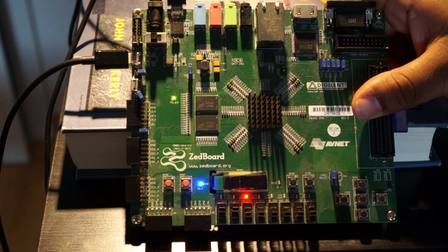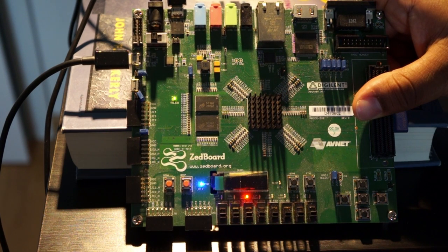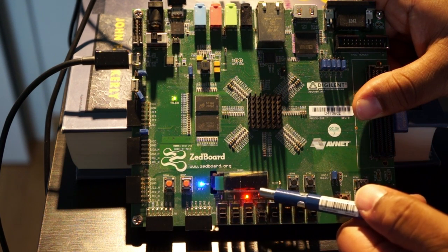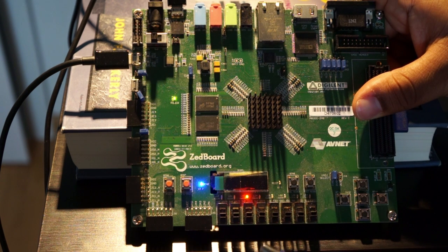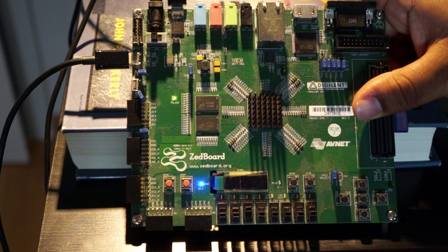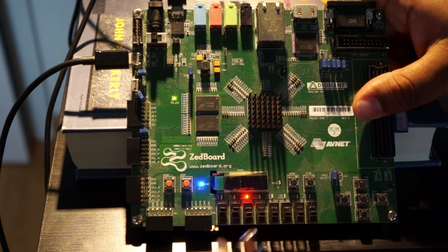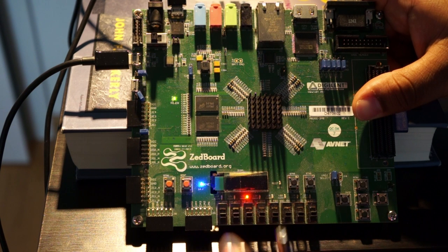Okay, now independent of whether the clock goes low, or if we change the input of the flip-flop, the output will still be memorized. Okay, the only detail is that we have an asynchronous reset, so at any state, if the reset goes high, our output is going to go low. Okay, the same thing for the low. If we now go to the rising edge of the clock and our input D is low, our output is going to be low.